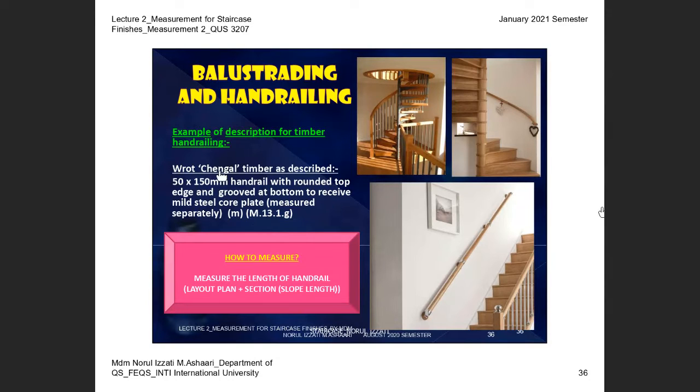Okay, Cengal is grade A timber in Malaysia. Like oak internationally, oak also has its own category. That is also one of the famous timbers. So you can put this one as the main heading because this is the general kind and quality. You refer back to section M. In general, we have to write kind and quality and the size. So the cross section must be written.